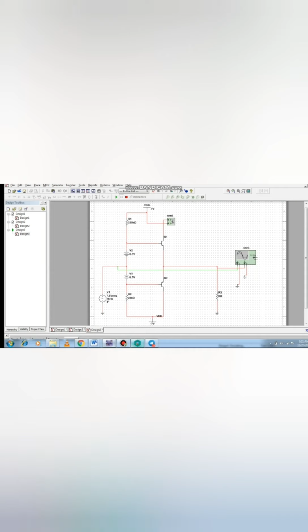the graph in the oscilloscope. More bias voltage given using bias voltage in V2 and V3, as shown in the circuit diagram, makes the operating point be above the cut-off point. Hence, the output waveform of class AB results as seen in the oscilloscope. The crossover distortion created by class B is overcome by this class AB. As well, the inefficiencies of class A and B don't affect the circuit.